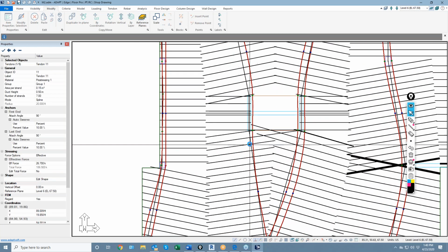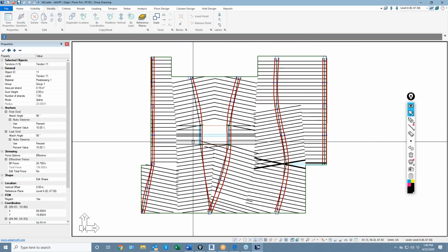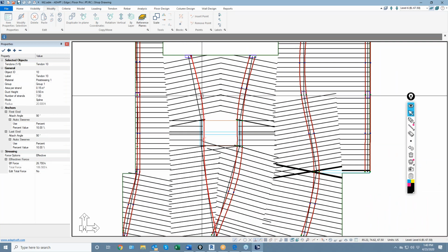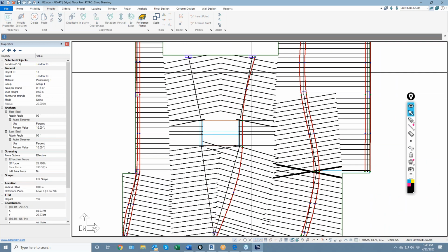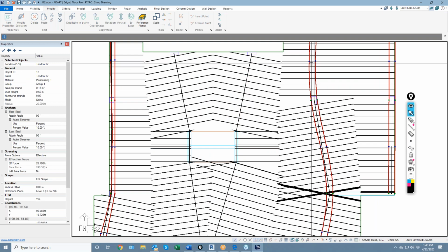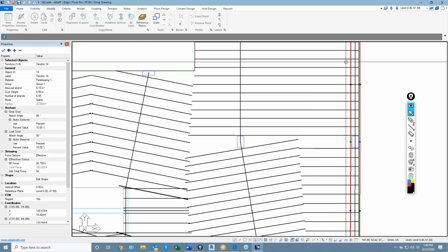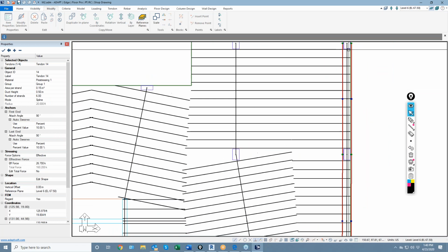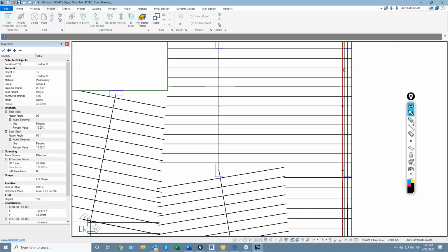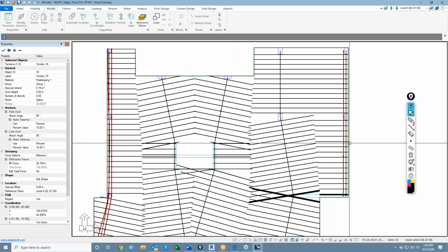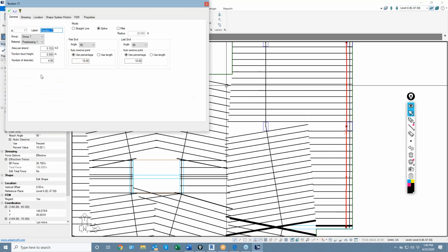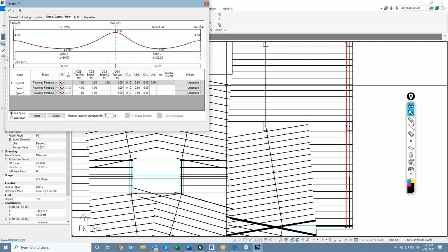I'm going to actually delete all of my cables. Yeah, let me delete these cables here. The nice thing about mapping is it's pretty quick. The time is taken when you're editing the cables. This one is already linearized. I'll just leave that one alone. I'll delete the one outside, and maybe this is a case where you use only one strand, but when I delete it, I have to remember to go and bump this up by a factor of 2 because I had represented it as 2 cables. You can see the shape of the cables there.